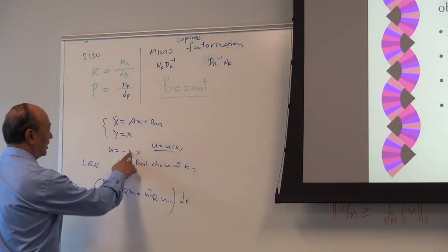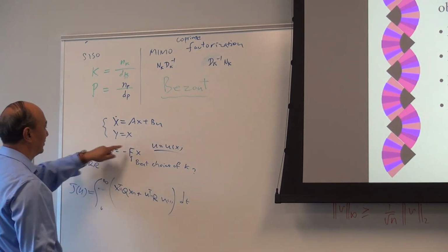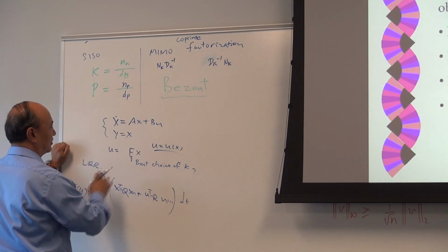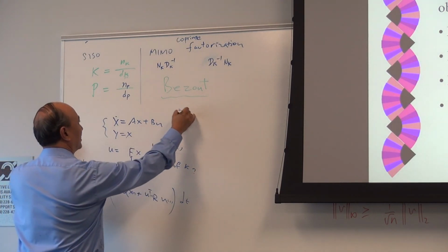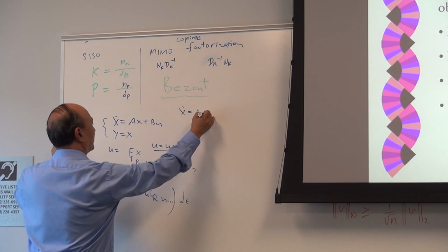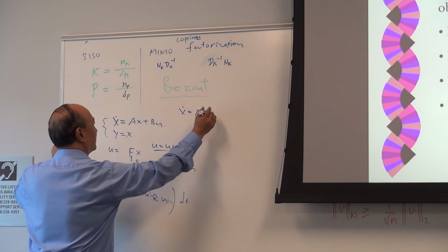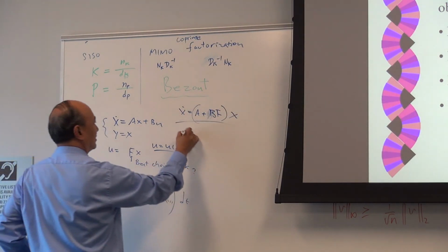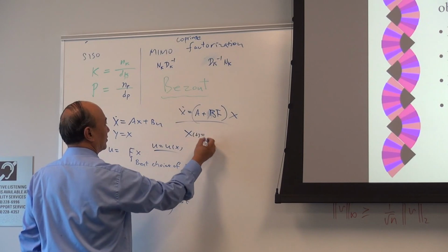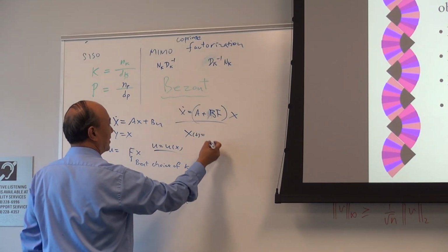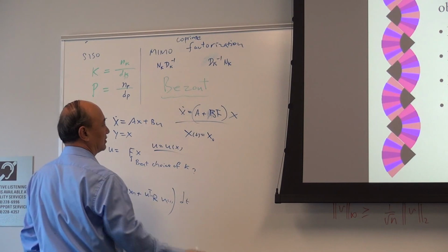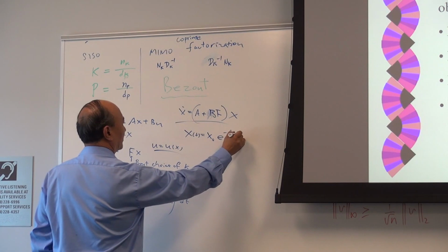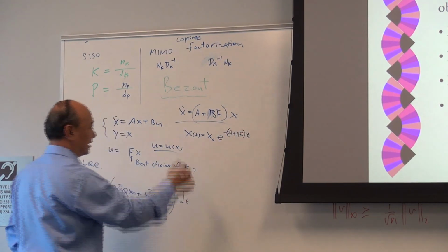Let's use F in here. If I put this one in, it doesn't matter; I remove this negative sign, it can be absorbed inside. Then my closed loop system is x dot equals A plus BF times X. Then I know that x of t will be e to the power of A plus BF times t, times the initial condition x0, that's a decay.